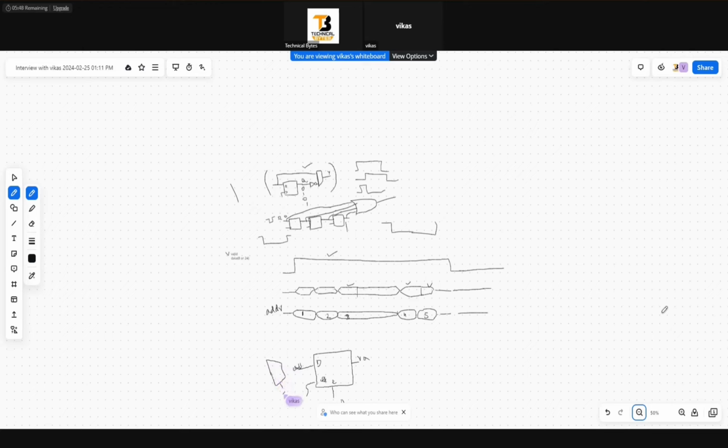So this mux, valid will be the select line for this mux. If the valid is 1, input address will go to this address. Otherwise, this registered version will be returned to this flip flop, based on this valid. The second input is this registered version of address. This is a mux saying whether the input address I should take or this registered address I should take. And for that validating signal, I'm using a mux here, so that whenever it is 1, this address we are always using in this registered address.